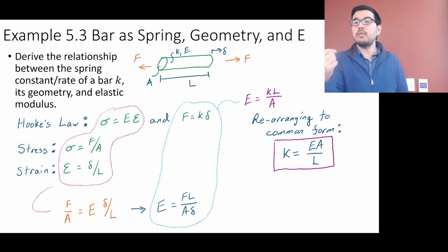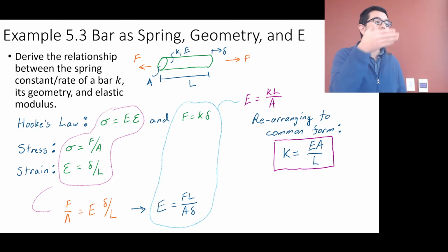And we say, hey, there are yield strengths, maximum stresses you can get to. So constant equals force divided by area. And we said the supportable load this bar can support is proportional to the area. So if I increase the area, I can support more force.